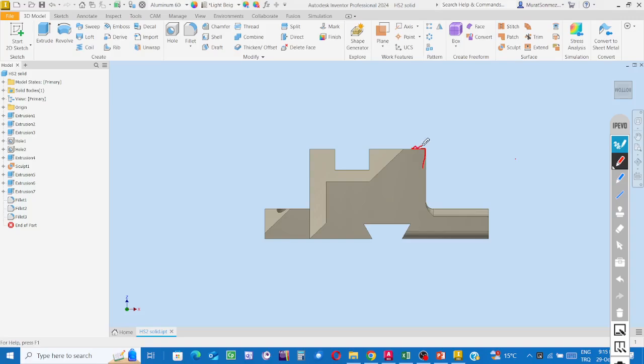Measure such a distance over the surface, measure the distance over the other surface, and then after marking these points, cut the material along this edge. Create an inclined surface. It is not a rounded surface, it's not a cylindrical surface, but it is a flat surface. At the end there will be an inclined surface along the edge, and the sharpness angle will have not one intersection but two intersections after cutting the material. For both, the sharpness angle is going to be greater than 90.